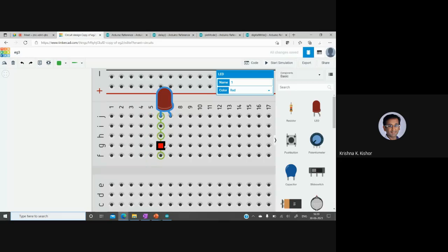So let's also place the resistor. So I need a resistor, so let's place that. And then, so this happens. So I can just place a resistor there. I'm placing it at two different points, and it's important. Why? Because if I do this, this is wrong. I think people in electronics will know this, because all these holes are internally connected. So it will be as though this resistor is not there. It will simply go through the wire that is there underneath the board. So I need a potential difference on two ends of the resistor. So I have all the components that I wanted.